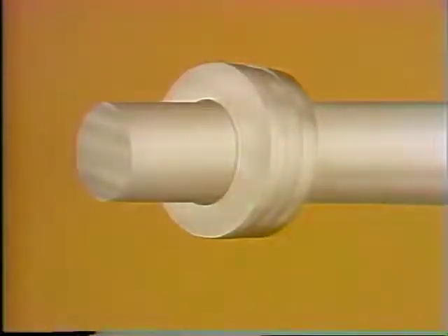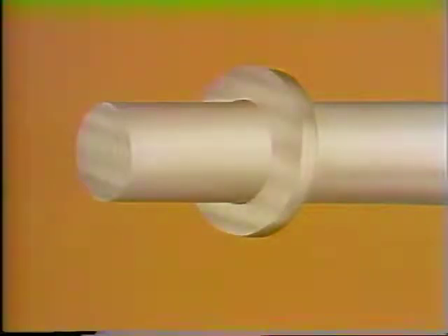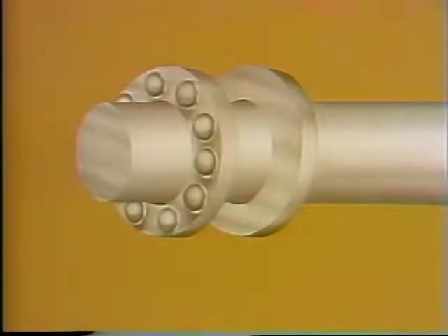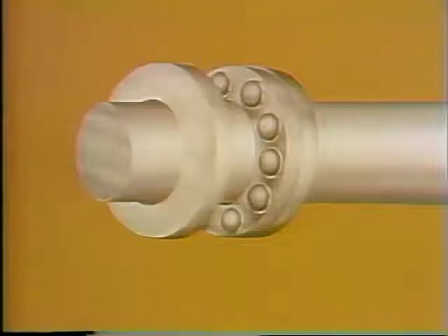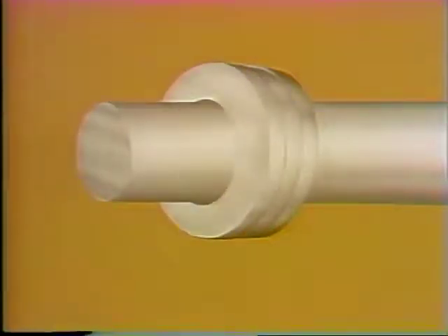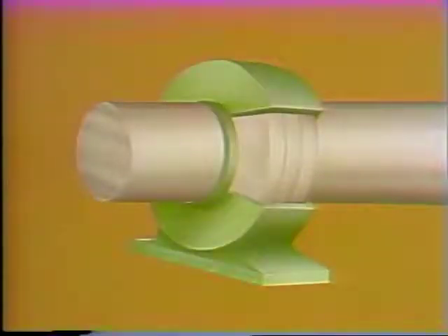A rolling contact thrust bearing, which prevents axial movement only, is designed differently. In this case, the shaft, like we see here, has a ring attached to it. The shaft and ring turn together. Rolling elements fit over the shaft and meet the rotating ring. A stationary ring also fits over the shaft and is placed up against the rolling elements. The stationary ring is attached to a housing. Lubricant keeps the parts from actually touching each other.